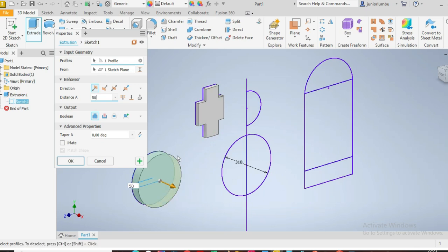So you can continue using the extrude button by doing this. You come there, you say plus. Now I come here, I want to add this one now, not this way but the other way, with how much, 70 millimeters. Then I type on my keyboard 70 millimeters, then I come here and click the other way.